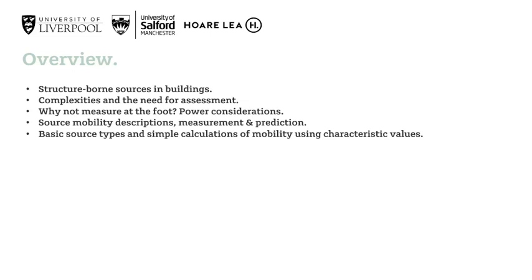From here, we'll remind ourselves why we can't simply measure at the foot of a machine and how, compared to an acoustic source, we need more than one descriptor when we're trying to predict power transmission. And at this point, we switch to the main focus of this presentation, which is source mobility.